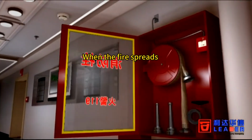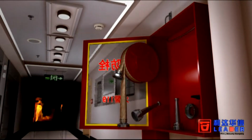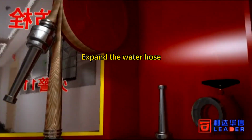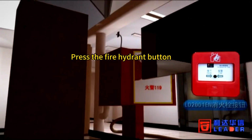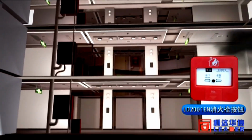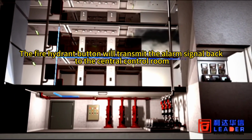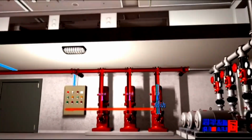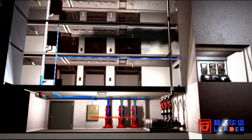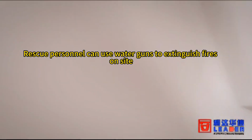When the fire spreads and it is necessary to use a fire hydrant to extinguish the fire inside the building, connect the water gun, expand the water hose, open the fire hydrant, press the fire hydrant button. At this moment, the fire hydrant button will transmit the alarm signal back to the central control room. Simultaneously start the fire pump. Rescue personnel can use water guns to extinguish fires on site.